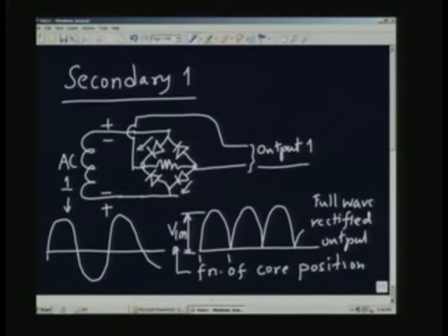This corresponds to this, I will say T by 2, this corresponds to this T by 2 here, and this will correspond to this half cycle, this will be T by 2. So something like this. So this portion has become this portion now, it has been inverted or rectified. So that is what the full wave rectifier is. In the sketch which I showed in the slide, if I had only half wave rectification, the alternate ones would be missing, these will be missing.